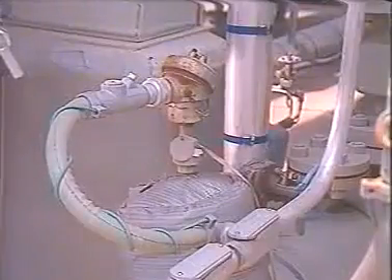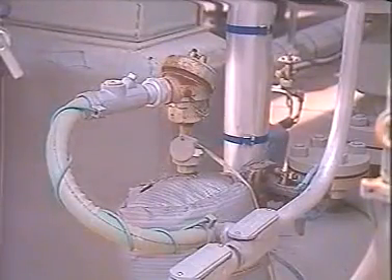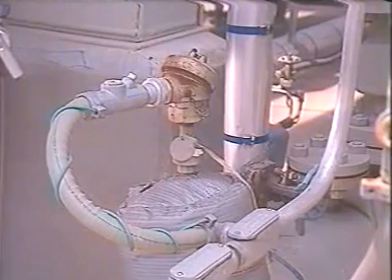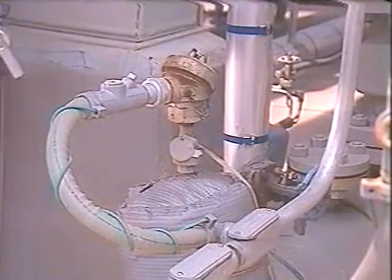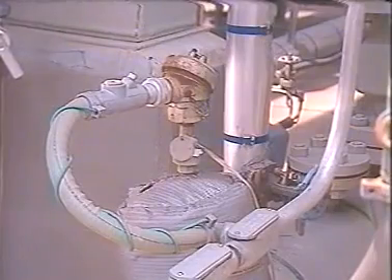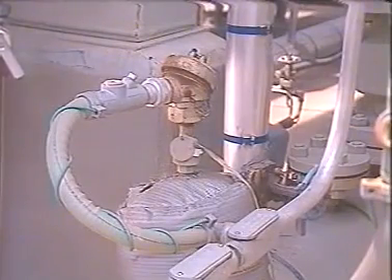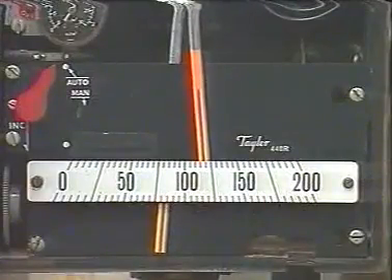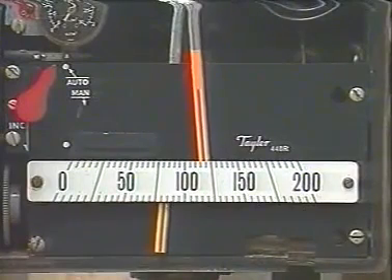First, there is a process that needs measurement and control. There must be one or more instruments as a measuring means that senses and measures the variable being controlled. The measuring means also transmits a measurement signal. A controller compares the measurement signal with a desired value called a set point.